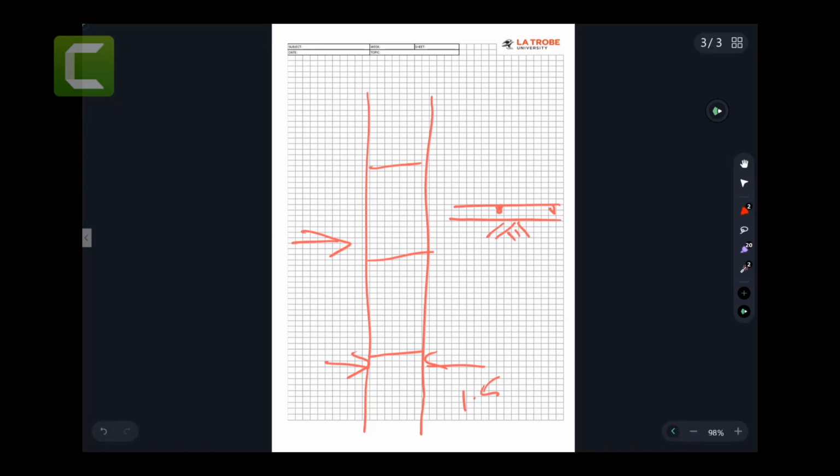Now, just for your information, as you know from physics, and as I just said, this is a plan view of a piece of concrete, whether it's suspended or sitting on the soil. How shrinkage works: the panel will aim to get shortened and shrunk towards its center of mass. So the best shrinking behavior will happen for a simplified shape, and the simplified shape for this is a square.